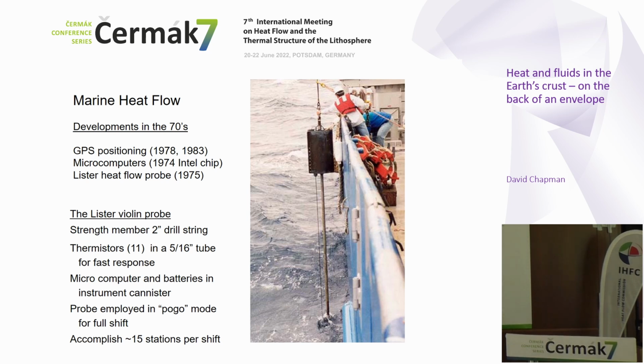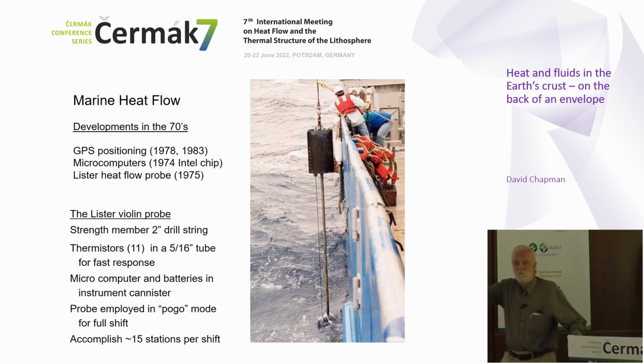So here's the strength member. It's actually 2-inch drill string. And then all the thermistors are in this 1 centimeter, very fast response thing. So this would never bend. You put it in the seafloor, and after about half an hour, you had your measurement. You pulled it out of the seafloor, and then you move the ship maybe 100 or 200 meters, put it down again, and then down again. So you could do 15 measurements in a day. And it was operational in what they call pogo mode. Any of you remember what a pogo stick is? You know, you jump ahead and so that's what was available.